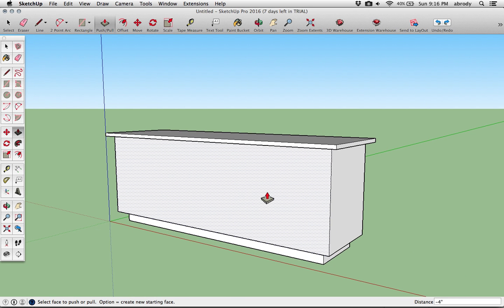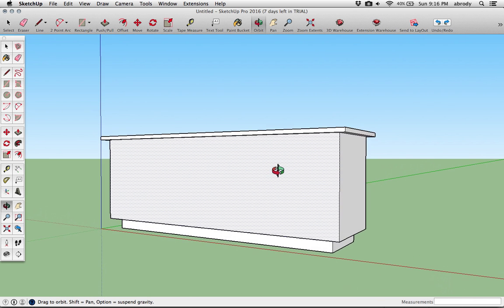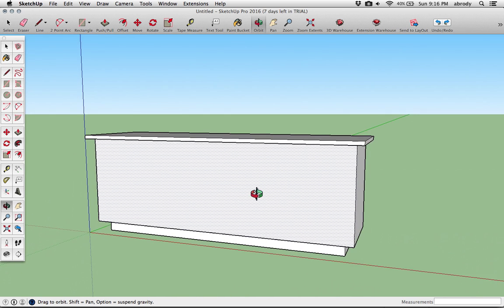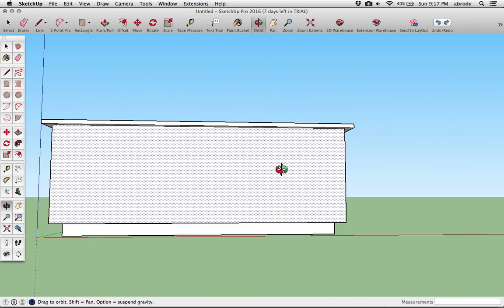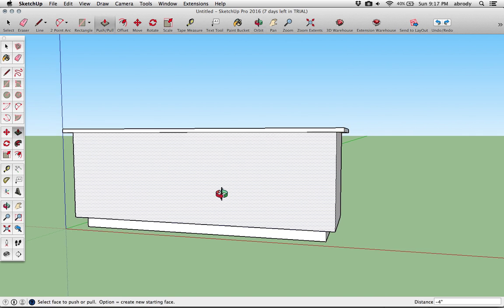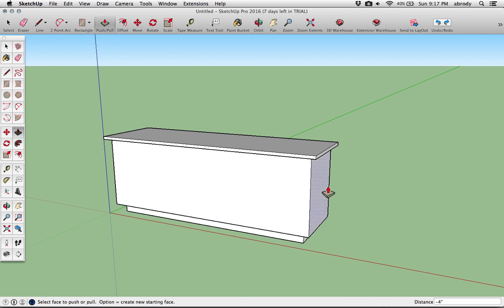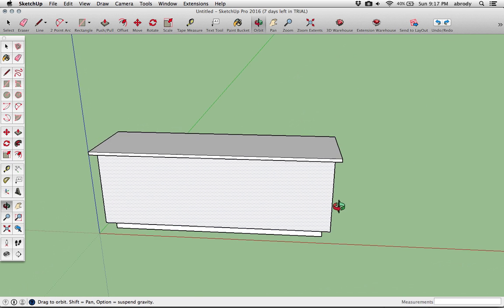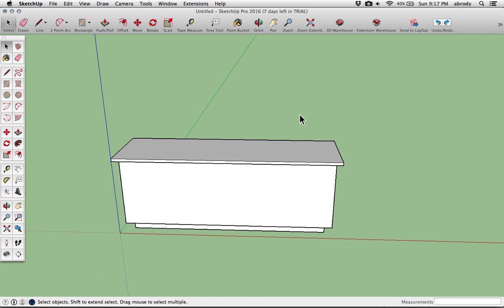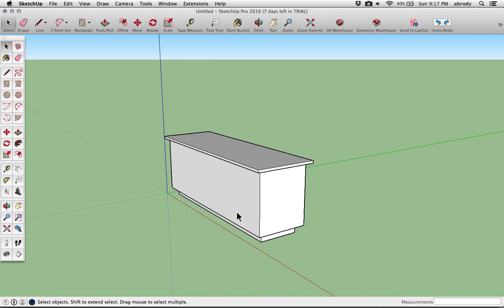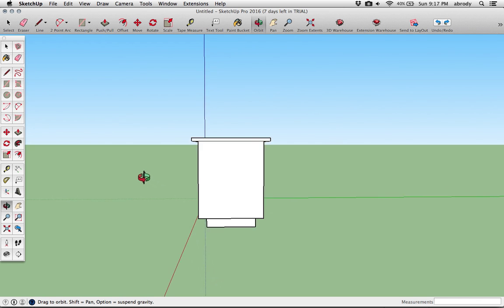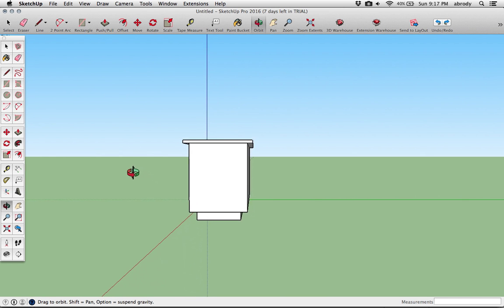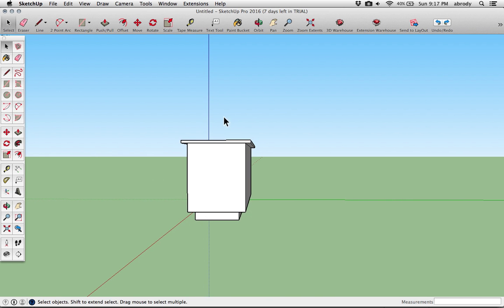Now, there are a couple of other features of SketchUp. First of all, if I want to make the counter longer at this point, of course it does get a little tricky because there's no kind of way to just stretch it. AutoCAD has a stretch command. But because everything is sticky, let's say I want to just make this counter deeper. If I put myself in a view like this, which is highly foreshortened, I can use my selection window.